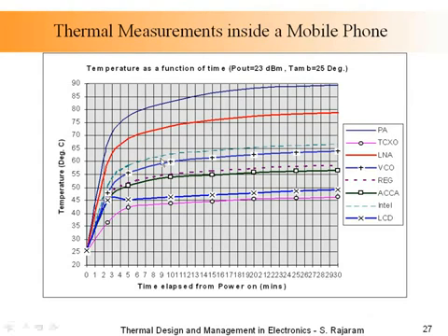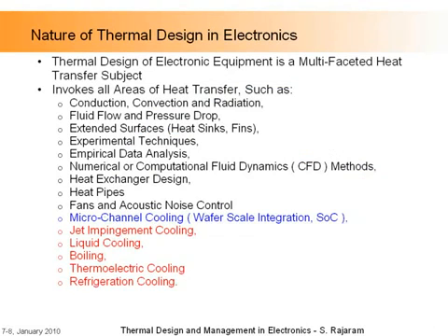I'm just showing you actual data from measurements inside this device. You can see this is the power amplifier, the hottest, and LCD is the display. The display also is running at 50 degrees C. Okay. All right. So we talked about this, the nature of thermal design. It's a multifaceted heat transfer subject.